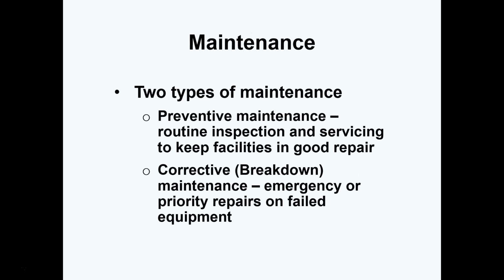There are two types of maintenance. You can monitor and service the part before it breaks to keep facilities operating efficiently, and this will be called preventive maintenance. And this is what we meant by knowing the mean time between failures. Then you know when it would fail the next time, and if you do that, you plan for preventive maintenance. You plan for that maintenance. Or you can wait until the component breaks or fails, then fix that component, and that will be called corrective maintenance.